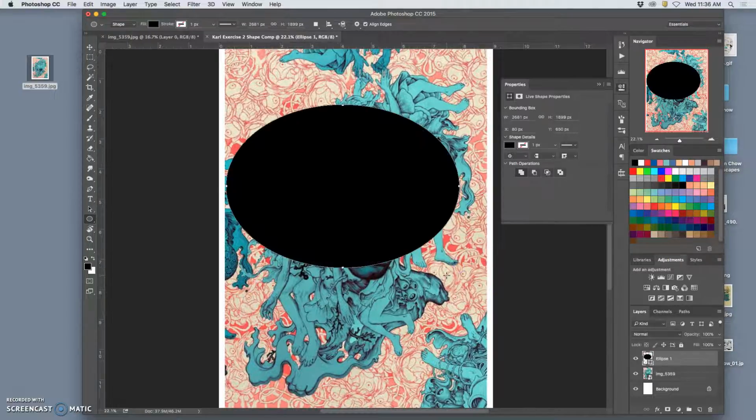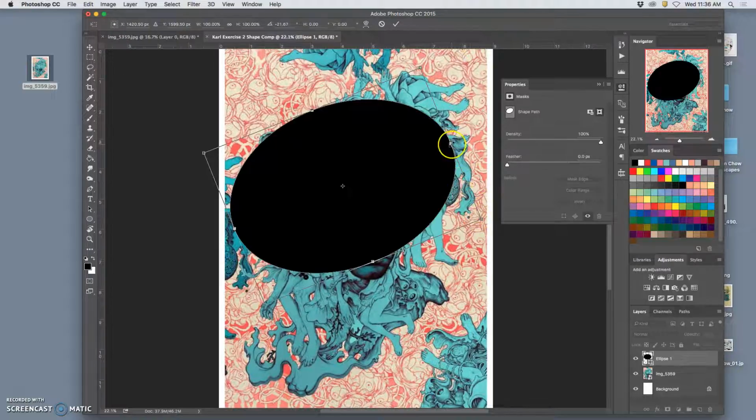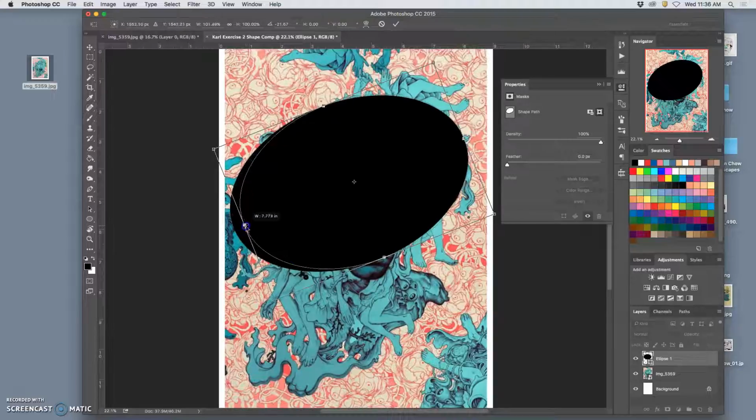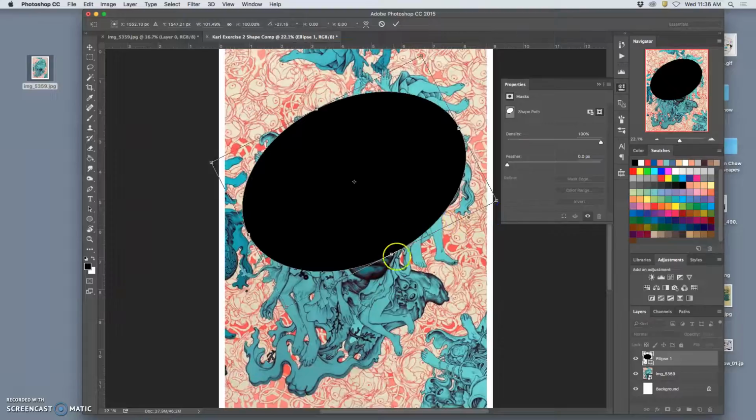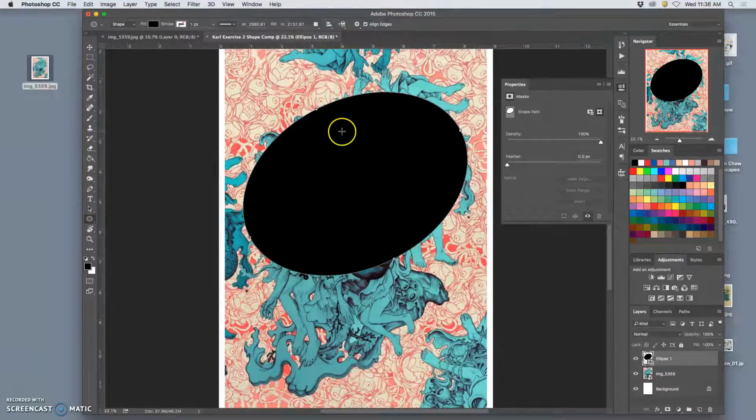And this is very much like the cartoon tool. Now, how do I make that oval the right size, the right angle? I hit Command T, just like we did for our cartoon, and that's free transform. It allows me to rotate it. It allows me to stretch it, nip and tuck it. It allows me to place it exactly where I want, and then hit return, and I've got my shape.